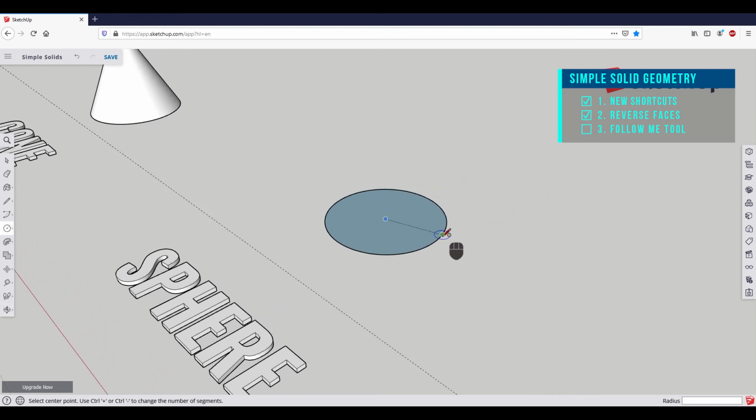We will place it at the center point of the first circle. If it's not snapping automatically, then just do the same like before. Move your mouse over the outer edge until the reference point is highlighted. Now, before you left-click, press the left arrow key to draw the circle along the green axis. Confirm the shape inside or outside the first circle.